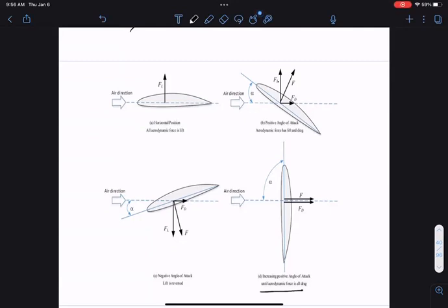So think about it. When you turn the blade, there's force. The lift force eventually becomes power. And the power has to go somewhere. The power has to go to the grid. But inside the grid, the power has to be consumed by some load. So it's actually not uncommon for wind turbines to be in a situation where they're generating too much power for the grid. The grid may say, I don't want your power because I can't dump your power somewhere.